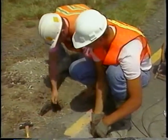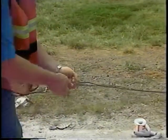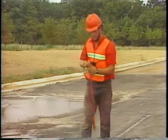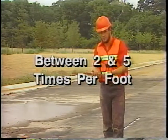After inserting the wire, you will have 2 lead-in wires from the beginning and the end of the loops. These 2 wires should be twisted together to form a pair from the loop to the pull box. Using a twister is a lot faster than doing this job by hand. To avoid crosstalk, you should twist the wire between 2 and 5 times per foot.